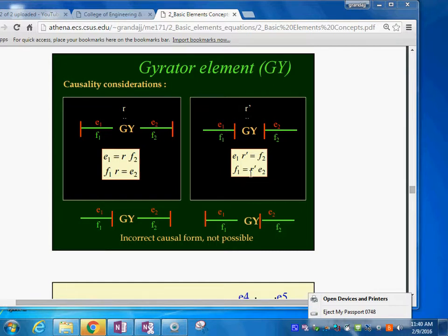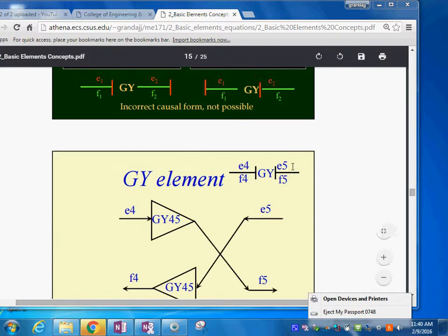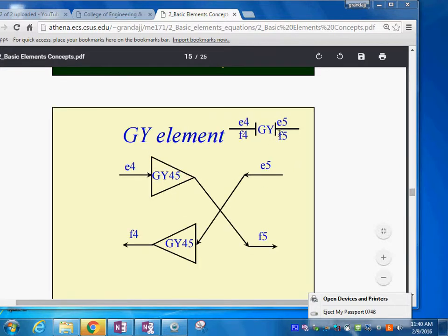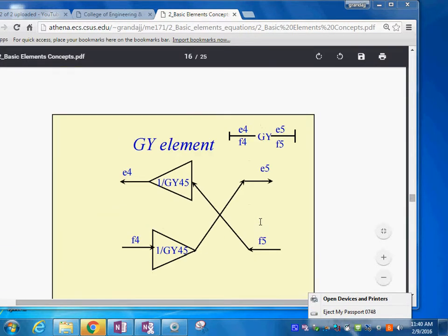The constitutive laws of the zero junction say that all the efforts are the same, but the flows will sum. In fact, if you have a T in a hydraulic system, water comes in towards the T, some goes one way and some goes the other way. It means whatever came in equals what got out. So it's totally conservative, but at the junction you have constant pressure, while the flows will add or subtract.